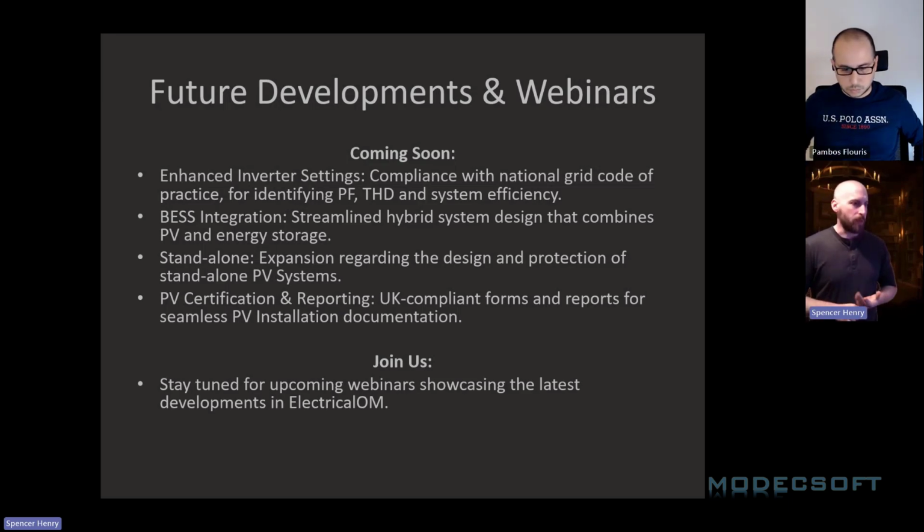So we are looking at enhanced inverter settings to do with identifying power factors, other harmonic energy efficiency within systems, and streamlining the link between BES systems so we can combine the PV and energy storage elements, so it's more interactive in the way they behave in the software.